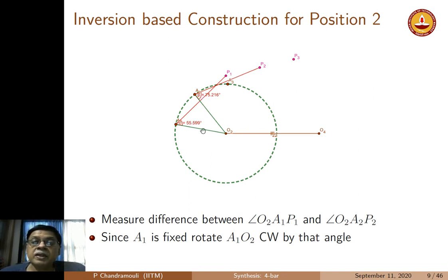The way that I figure out A2, remember I said AP is a fixed distance, is that from P2, I can draw a line of that distance where it intersects, which gives me A2. Similarly, from P3, if I draw a line A3 P3 whose distance is equal to A2 P2, which is equal to A1 P1, I can locate A3. So essentially you cut an arc.